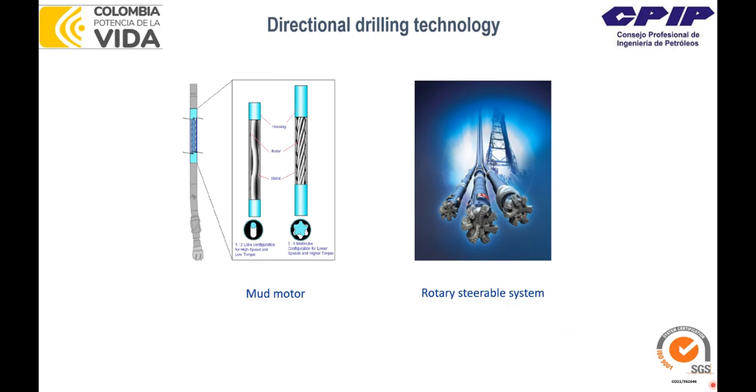There are still two main tools on the market: the mud motor, which is simple, reliable, and cheap, but with some limitations, and the rotary steerable system. Almost every big service company right now offers its own rotary steerable system. Okay, and now we'll look a little bit into details. Let's refresh the difference between the principles of drilling with the positive displacement mud motor and the rotary steerable system.